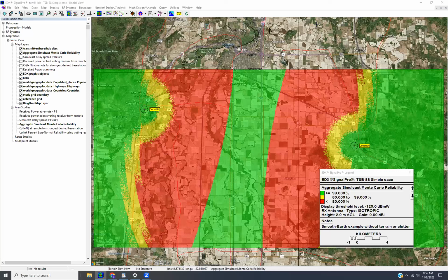And the way I would add one of those is to just go ahead and add a site into the project. And I'll set up my receive parameters however they are. Chances are this one's going to be much lower to the ground, maybe on a utility pole or something like that. And when it comes to the transmit parameters, you can disregard these, because what you'll do is just leave this sector out of the transmitter group when you run your downlink studies or your talk out studies.